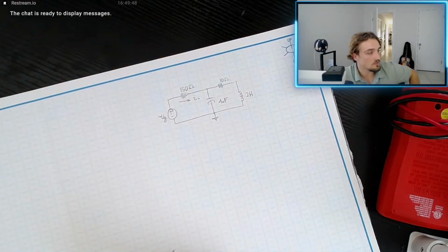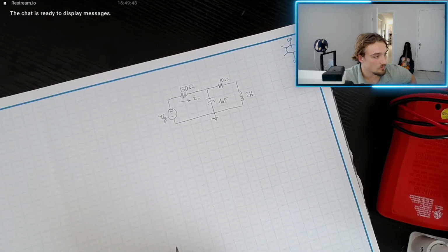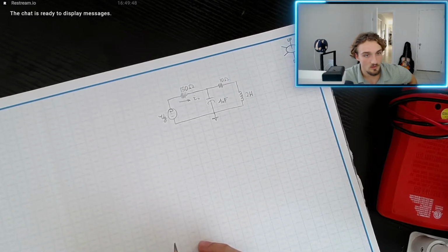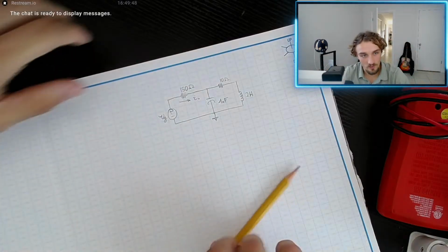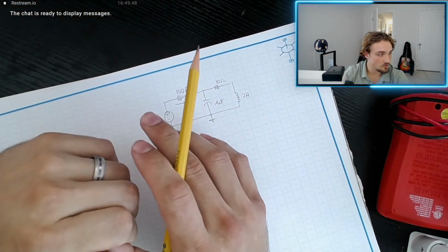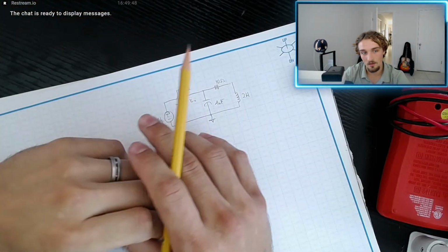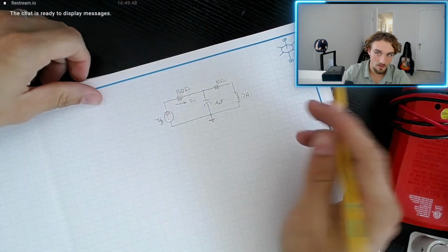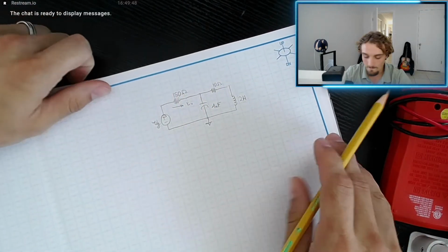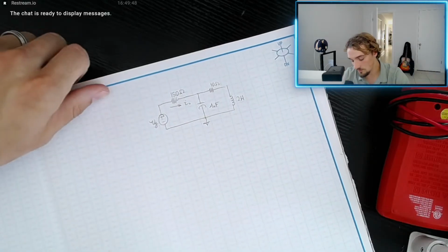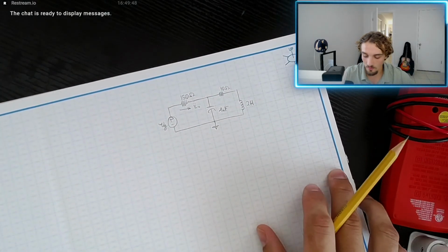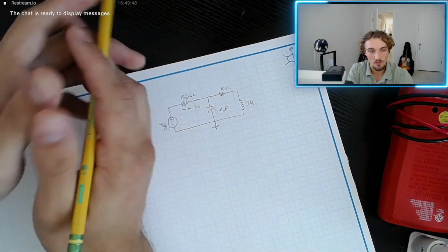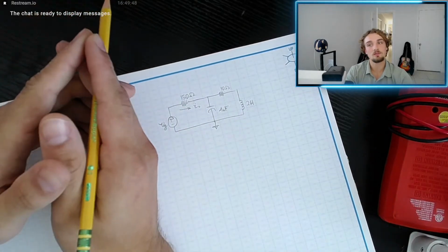Now, the frequency of the sinusoidal voltage source in the circuit is adjusted until the current I naught is in phase with VG. Right, until I naught, I'll call it I out, is in phase with VG. Okay. So to my understanding, this would mean that the imaginary part of the impedance would equal 0.